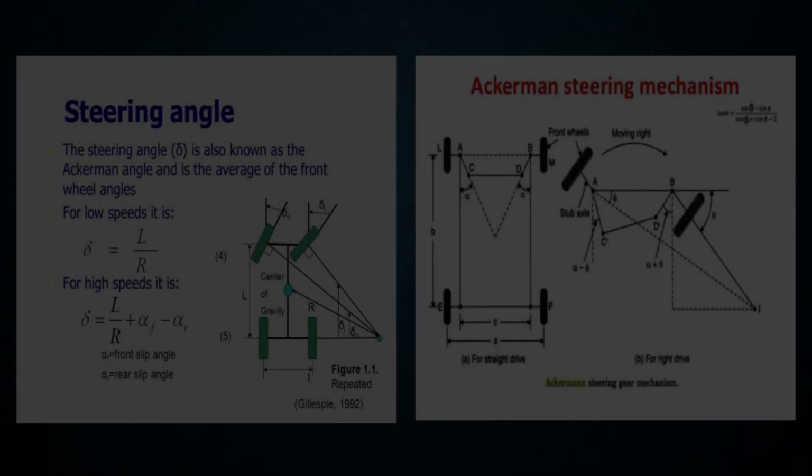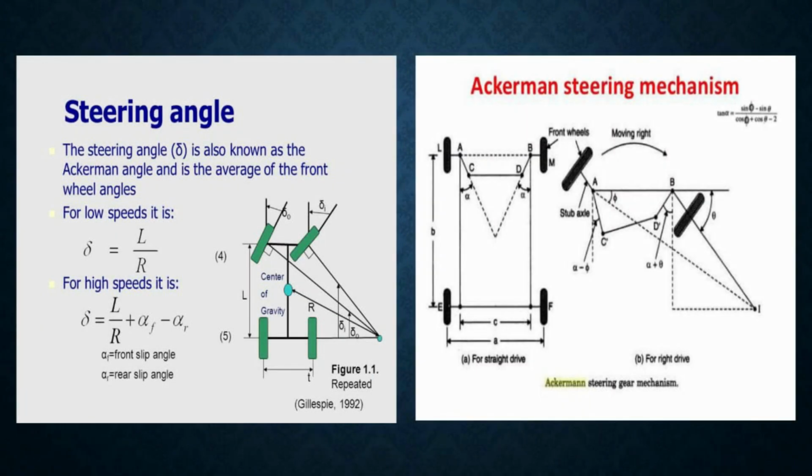Hey everyone, this is Milan Chaudhary. In this video, I am going over the Ackermann steering. The name Ackermann comes from a guy named Rudolf Ackermann who actually patented this idea. Back before the Ackermann steering was around, some of the tires may slip because they come to a different point. The reason Ackermann steering exists is so your tires do not slip when you go around a corner.